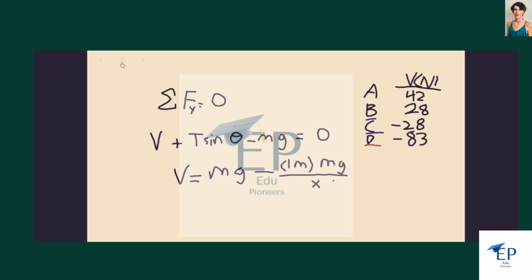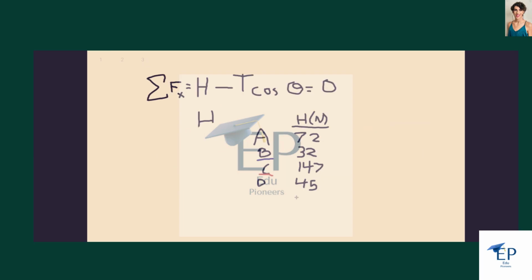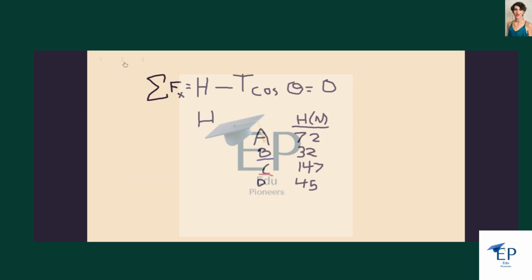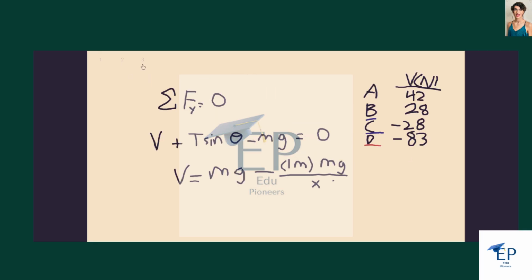Looking at things where the force was the largest, it was case D over here. It's actually a pretty small horizontal hinge force, but a pretty large tension in the cable, so I probably would not pick D. Case C has the largest cable force, also by far the largest horizontal force in the hinge. A low vertical force, but still I wouldn't pick case C either.